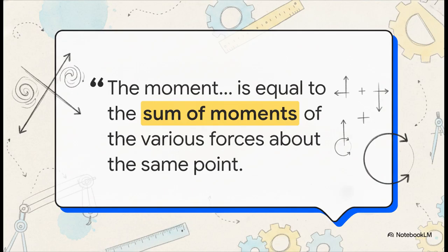Instead, you can just easily break the force down into its simple horizontal and vertical components, calculate their individual smaller moments, and then just add them up. The sum of the parts perfectly equals the whole. It literally saves engineers countless hours.